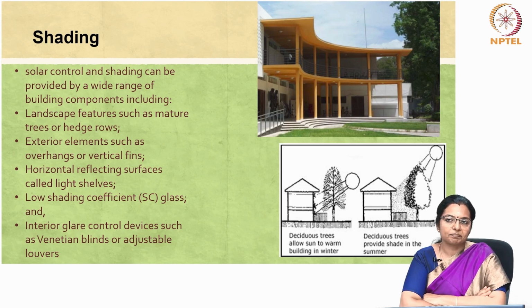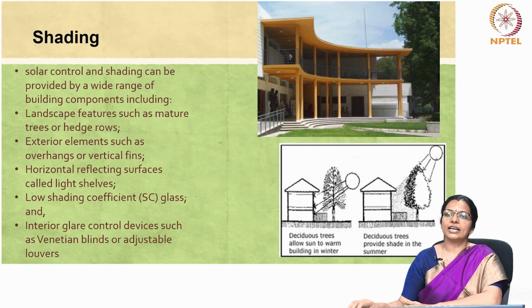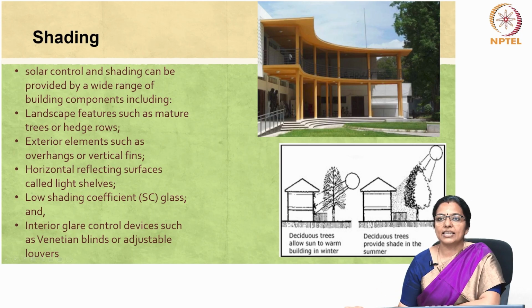Structural controls like external shading devices are essential environmental controls that either obviate or greatly reduce the need for mechanical heating and cooling to maintain thermal comfort inside buildings by controlling heat gain through openings. Along with glazing type and size of the fenestration or window, shading devices are equally important in limiting heat gain from outside through radiation. External and internal shading devices can thus be used as an essential solution for achieving energy efficiency.